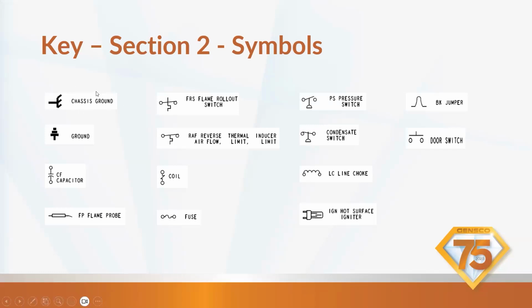As you can see here, we'll start right up here on the top left. You're going to have a ground wire, and it could look like two different symbols for where it's connected to ground. It may be this little pyramid, or Devo hat as I like to call it. It might look like this little antenna here, right? So find out what your schematic is using for a ground. These are both out of Trane furnace manuals, so they use two different symbols for ground depending on the manual you're looking at. If you're not sure where the ground wires are, look at your key for the symbol, and then you can find those symbols on your schematic.